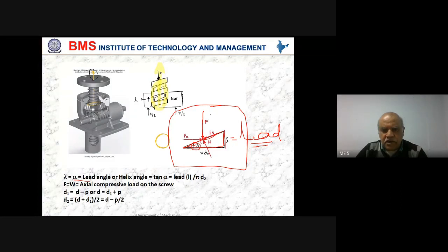And then F is the load that is acting on the screw thread. N represents the normal reaction force, and this distance will give you the circumference of the thread along its pitch diameter, denoted pi dm, or in our case pi d2, which is the circumference of the pitch diameter. F is the applied load or weight to be lifted, and N is the normal reaction force, and small f or mu is the coefficient of thread friction between the load applied and the threads.